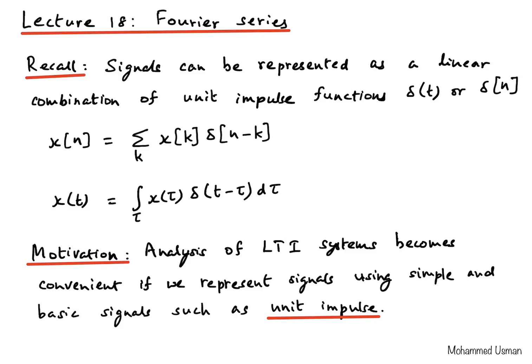Towards the end of the previous lecture, we discussed that the concept of Fourier series utilizes the complex exponential signals in its mathematical formulation. And today, in this lecture, we will establish the importance of the complex exponential signals in the context of LTI systems. And then we will see how we'll have a motivation to understand why the complex exponential signals are used in the Fourier series representation of periodic signals.